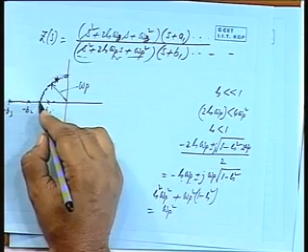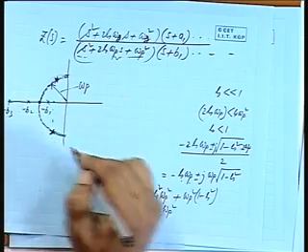The roots will be here, there will be two roots here, is it not? So, that time we will get 1 by s plus omega p whole square. At zeta equal to 1, the quadratic is s squared plus twice omega p s plus omega p square.